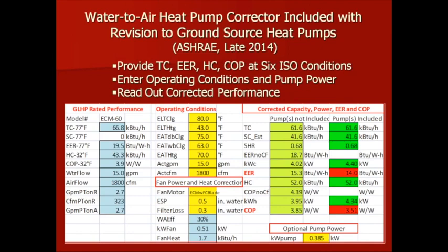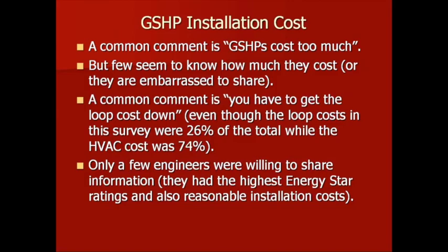As they mentioned previously, we do have a rewrite coming out of the book, Ground Source Heat Pumps, available from ASHRAE, and in that we'll include some spreadsheets that will allow you to correct the performance of these machines from the rated conditions. This is just a screenshot of one of those things. It's a tool that we try to get to folks so they use engineering data rather than marketing data to design their systems.